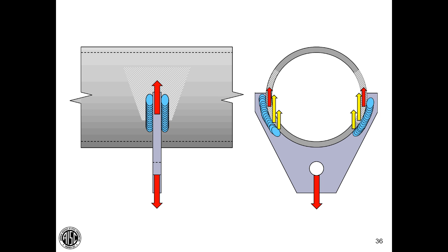Now, if you have to seal this up for architectural reasons or for painting or something like that, by all means, go ahead and do that. In terms of sizing the weld, designing the weld, we need to understand that that's not going to be loaded uniformly along its length, and the ends are the portions that are going to do the most amount of work in this case. Let's go to square tubes.